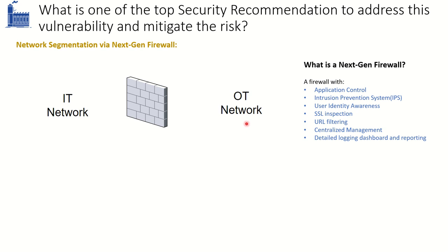Usually that is a common scenario whenever a vulnerability is released in any of the OT devices, in any of the PLCs. The vendors will release the patch, and then the firewall vendors will also release an IPS signature for that attack. They will study the attack patterns, develop an IPS signature accordingly, and send it out via an update to the firewall. And you simply have to enable that IPS signature, and then that IPS signature can act as a virtual patch. It will drop the traffic for the attacker's attack.